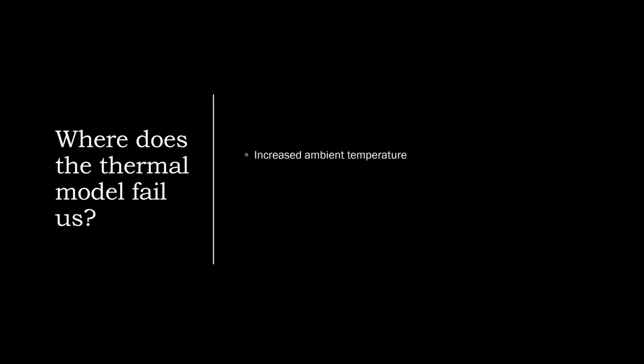The motor thermal model, as I understand it, in the 369 and 469, it may be different in the 869. I am waiting on an answer back from our mutual friend, Terry Smith. But at least in the 369 and 469, the ambient temperature is not taken into account whatsoever. So a thermal model for a motor in a pump in Antarctica and a motor in the Sahara Desert, the identical motor at the exact same speed and torque will show the exact same amount of thermal capacity used. And we obviously know that that is most likely not true. The heat will dissipate from that motor in Antarctica much faster than it will in the Sahara Desert.